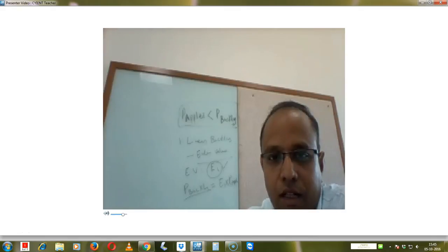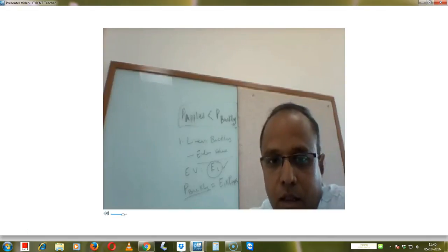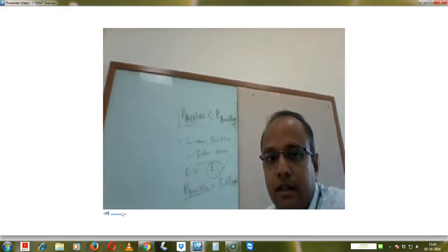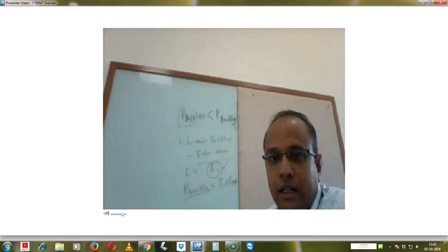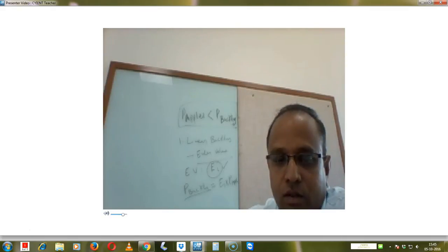Buckling loads for several configurations are readily available from tabulated solutions. So if you take simple configurations like this type, you can directly go through hand calculations. No need to do stress analysis. But if our geometry is so complicated, then we need to go for a buckling analysis in the finite element method. If the geometry is very simple, like a simple rectangular cross section, the only tough things in this equation are the I value and the L value.